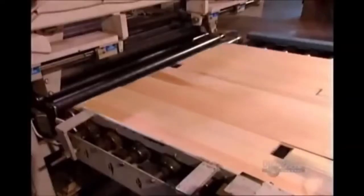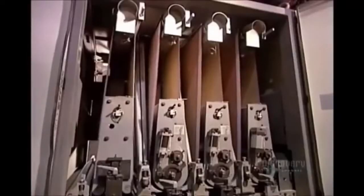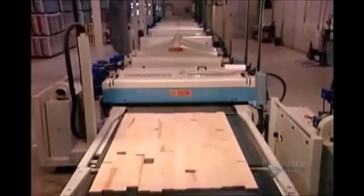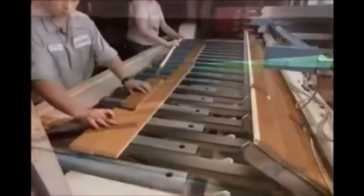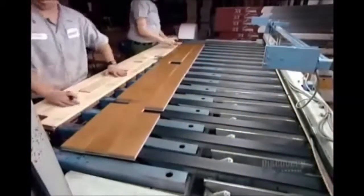This will be pre-finished flooring, so the pieces now run through a sander to prepare them to receive 8 coats of varnish. For certain finishes, the first coat contains wood stain. All subsequent coats are colorless. Between each application, ultraviolet lamps dry the varnish in just a few seconds. As the flooring exits the last drying oven, it's ready for packaging.